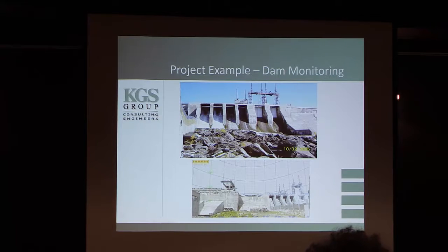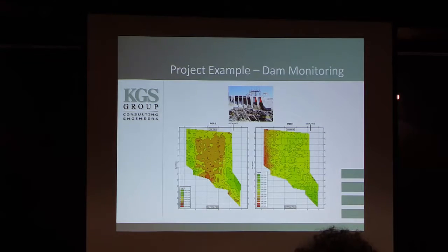We did a 3D scan on it, derived a 3D point cloud model, and then from that we did analysis on it. Because on a 3D scanning side we're to 2-3 millimeters of accuracy, we can start performing analysis on the face of that dam, and start monitoring spalling and wear on that concrete face, and then start doing differentials across it and highlighting where it may have worn past a threshold that would be desired. And I'm going to hand it over to Brook.